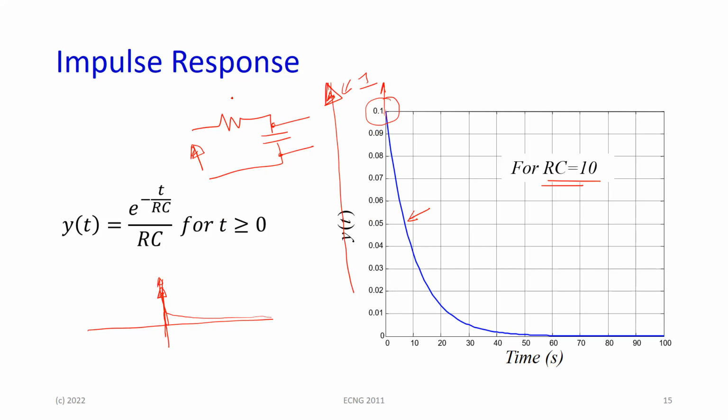So for instance, when you turn the sudden voltage on, this is charging the capacitor. If you make this too small, the current charging the capacitor will be too big and you can burn the capacitor or blow it. So that is the purpose of this kind of testing. This is a simple RC circuit, of course, but by imposing an impulse on it, you see, wait a minute, is it going to respond or is it going to over-respond, try to respond too fast? And in some cases, the thing just burns.